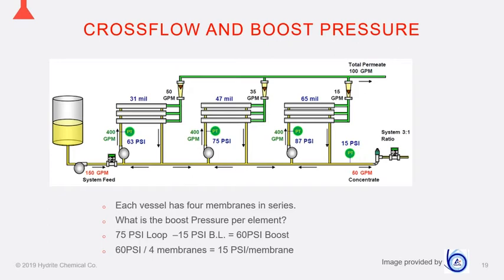For this example, it says 15 psi. Now, if I was to put a pressure transmitter on the outlet of the vessel coming down to the baseline on each of these loops, you will see that that number will still be 15. So it's the number going in and the number coming out. We see a pressure drop, and we want to see a pressure drop. A pressure drop is an indication of flow.